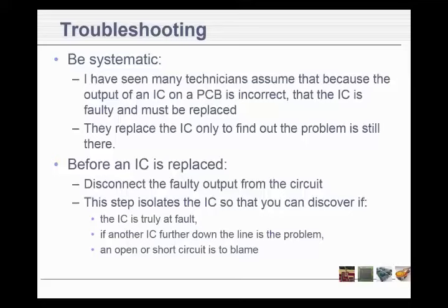Before an IC is replaced, I don't know how many times I saw people take ICs out and bend up the pins and throw them away, and it was a good IC. It wasn't that IC's fault. It was the next one down the line that was pulling this one's output low. So it had some input problem where it was shorting out to ground.